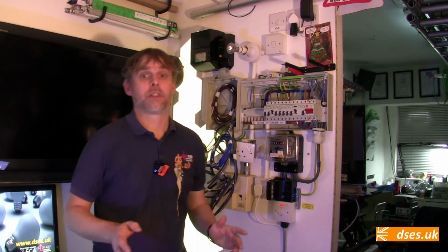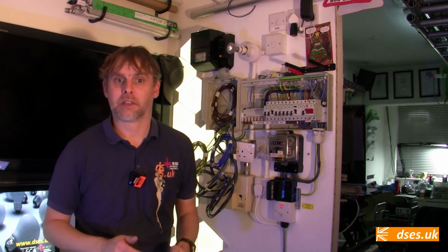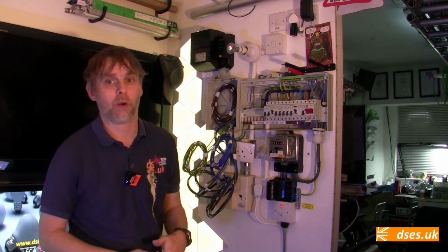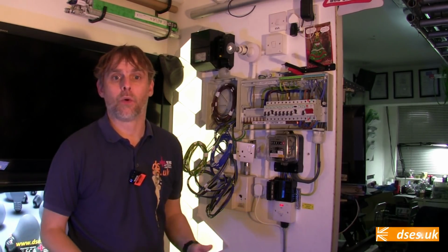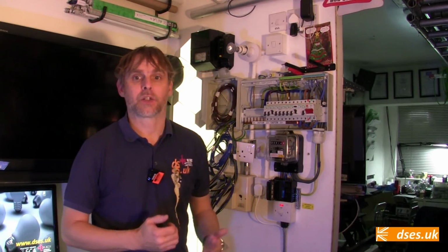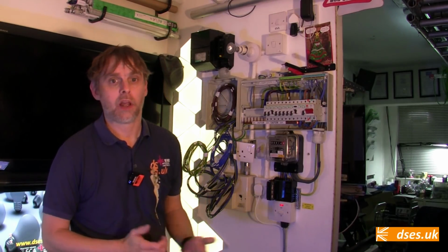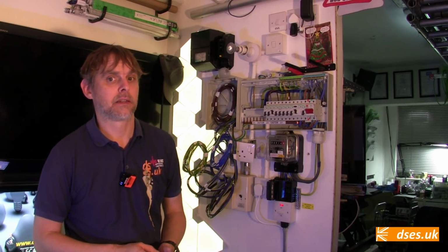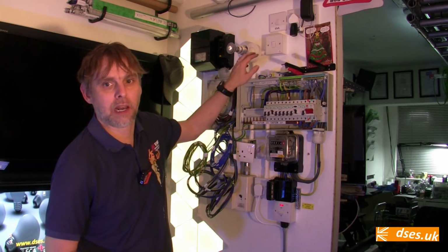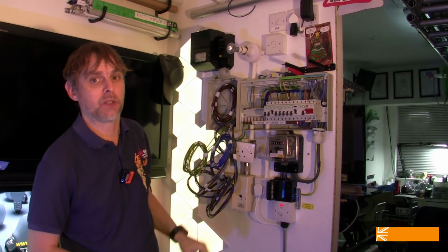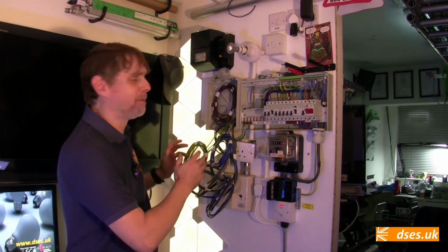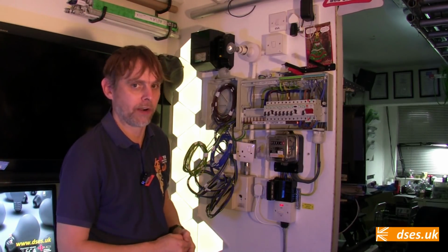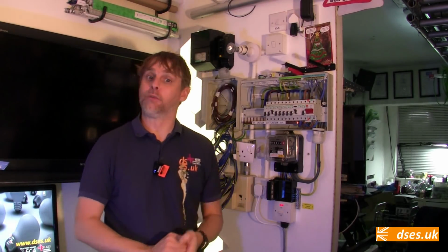That's okay, the principles are the same, it's just that the capacitance is happening on your switch wiring, probably because it's long and or it's 2 or 3 way. It runs along or near a source that is creating an electric field, and switch wiring often contains no neutral, and on old installations perhaps even no CPC to dampen the effects. Here, my switch is adjacent to my lamp holder, so it was more practical for me to introduce the volt onto the feed wiring to demonstrate this today, but out in the world it will mostly occur on the switch wiring. Jolly interesting stuff, I'm sure you'll agree.